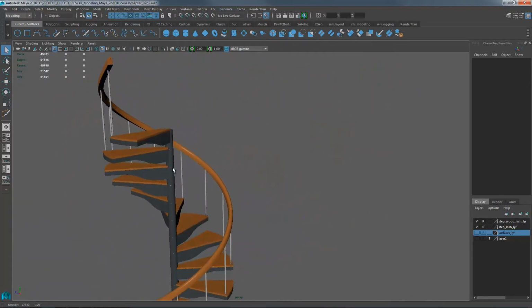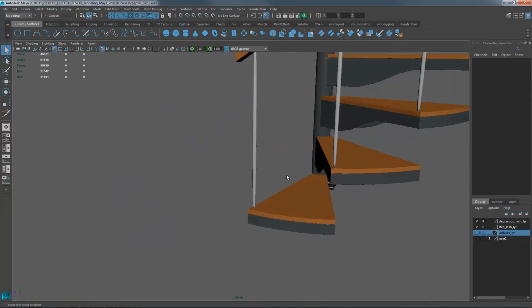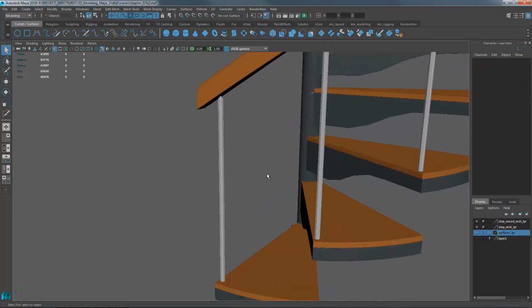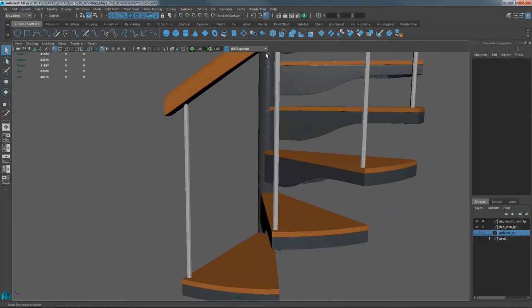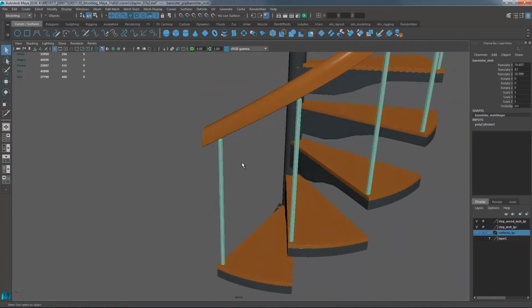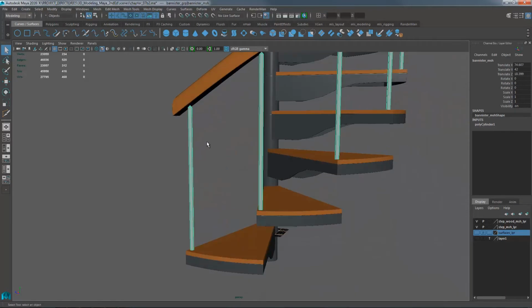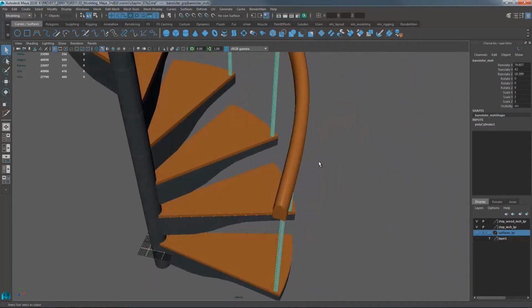Okay, next up is to match banister for 5 of them. Match banister along the changing heights from step to rail. Okay, my objective here is to make one good clean set of 5 and then reuse that set of 5 with instantiation.